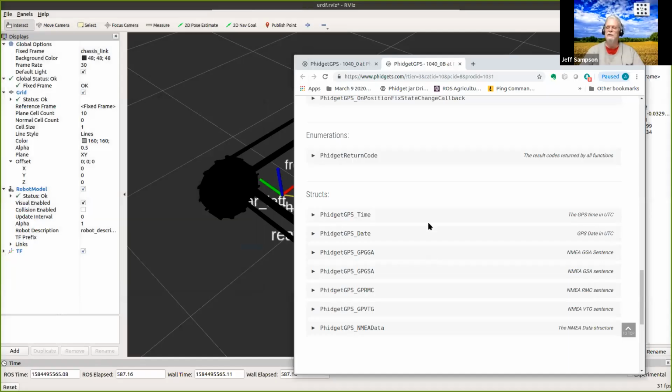I was talking about getting the raw data, the satellite data out, because you can do your own RTK, or you can do post-processing if you have that level, but it doesn't look like this one provides that level of raw data. And they might say that it has binary output data, but that's basically like the NMEA data, just in a binary format. That's not like the phase signals and the satellite distance signals that Kyler's talking about.